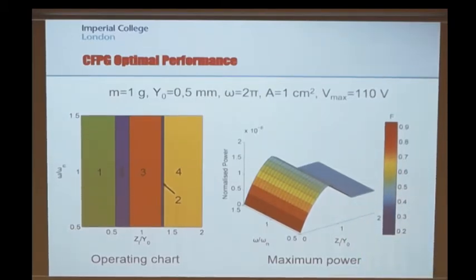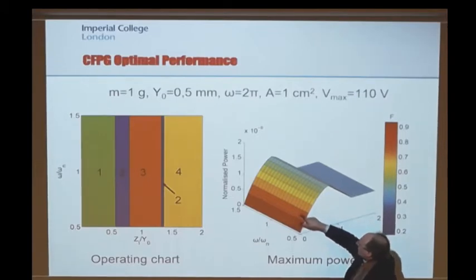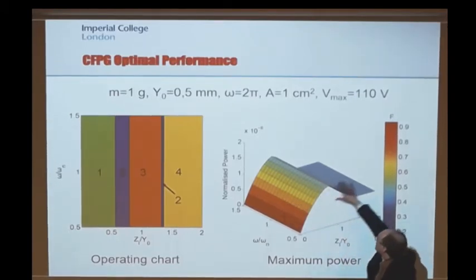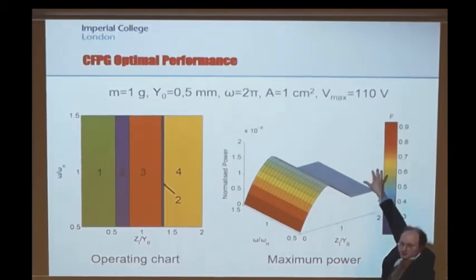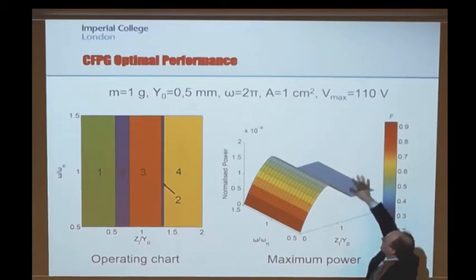Now, what you remember, hopefully, for these plots that we saw with the resonant type of approach was that when we were operating at resonance, we didn't get very much benefit down in this region of the graph, but as we moved over here and the devices got bigger compared to the amplitude that was exciting them, we got a significant resonant gain.